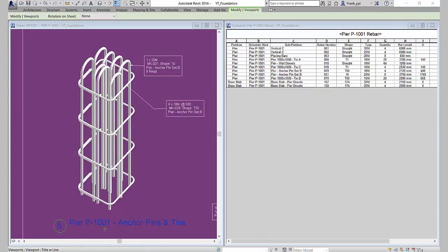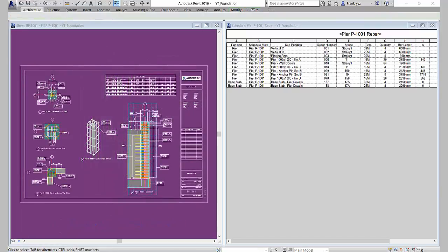This illustrates the fundamental difference between Revit and AutoCAD. The views on a Revit sheet are not copies of views, and the objects within the views are not copies of the object. What you see on a Revit sheet are in fact references to the actual views of the model. In the AutoCAD version of this project, every line and every piece of text on the AutoCAD sheet was stored locally within the AutoCAD file. No XREFs were used.